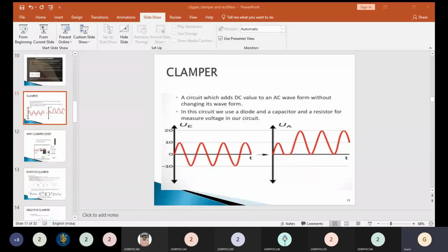Whether it is full wave or half wave, first you write the question. A full wave rectifier uses two diodes. The internal resistance of each diode is called Rf. Rf is nothing but the internal resistance of each and every diode. A full wave rectifier means two diodes, so all the formulas and values will have a factor of two, twice the value of half wave. So while writing the formulas, be careful in that part.